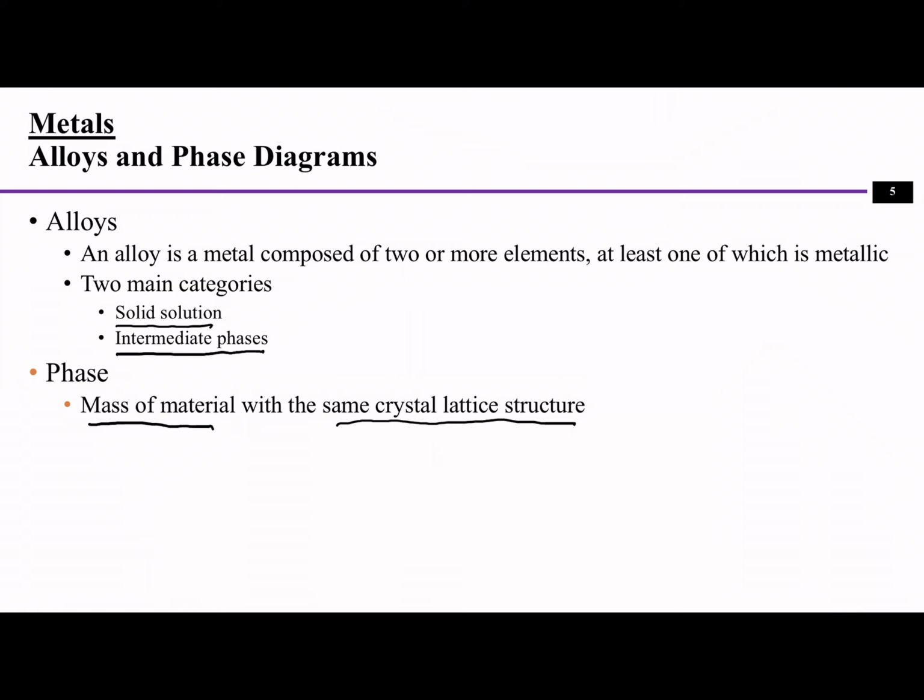If you put the metal under a microscope, sometimes you can see different structures. The reason is that it's not pure. There are also some other elements. It really depends on how much of the other element can be dissolved. If it exceeds a certain limit, then we'll form another structure next to it. So that's why there are different phases.